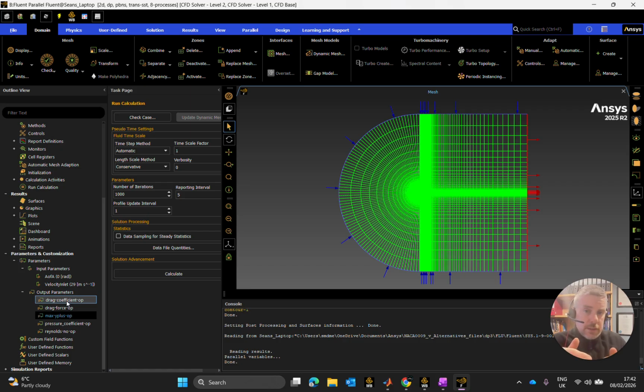I just want to make sure that they're all low enough to make sure that the turbulence model, which I'm using the SST again on this, remains robust. So again, I want to make sure that my Y plus value does not exceed 1 anywhere along that airfoil if possible. So that's what I'm going to keep that one for.